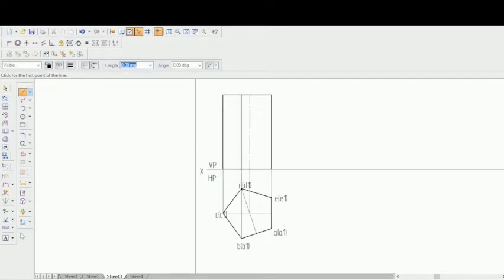Now we'll have to name those. Name the front face as well. When the observer sees from here, wherever I place the cursor, this A will be visible while E will be hidden. Similarly, A1 will be visible while E1 will be hidden. So how will I draw it as A? This is the bottom face. It will be A1 dash, and in the brackets E1 dash, as E1 dash will be hidden.